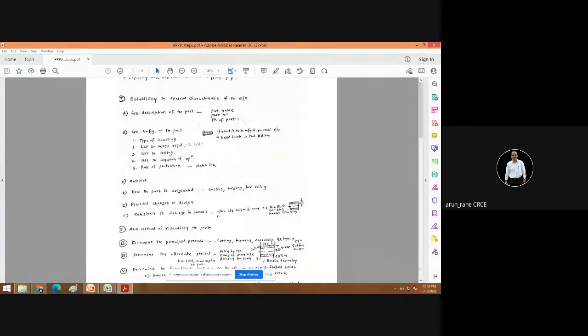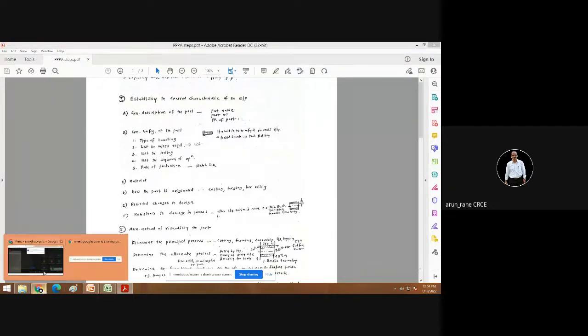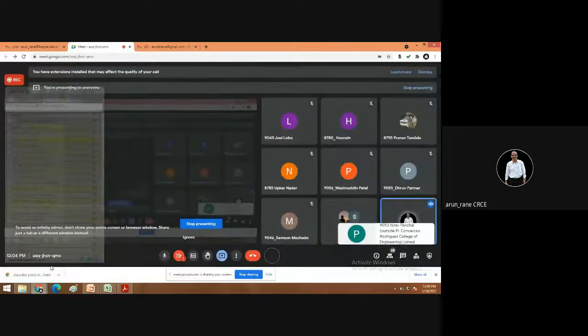So this is a thin walled component, a bush. Even if you apply little force, this thickness is 0.5 mm and the length is say 50 mm. Even if you apply little force, जो round shape है, it will become elliptical. That shape will get collapsed.